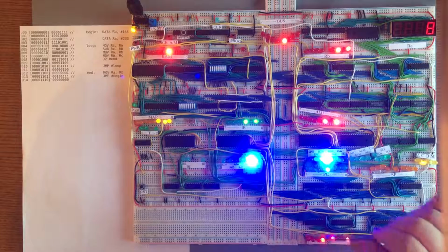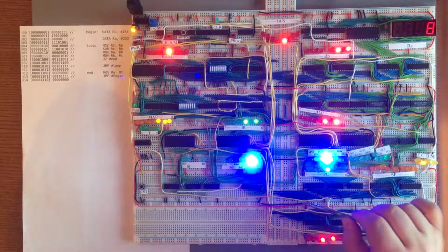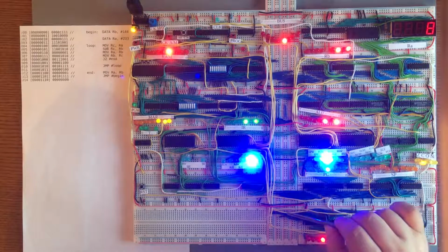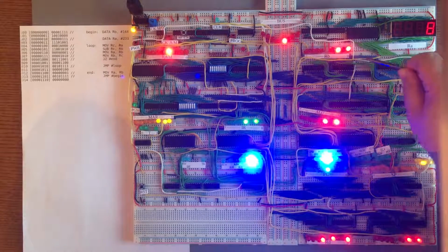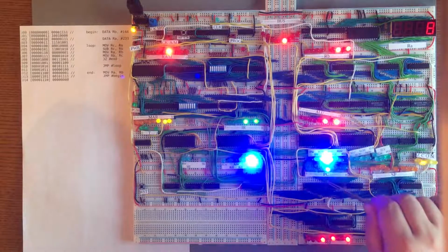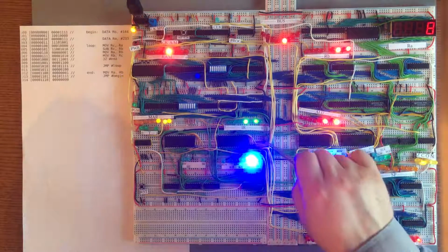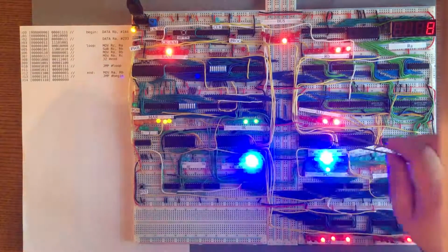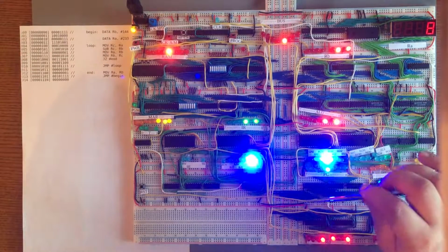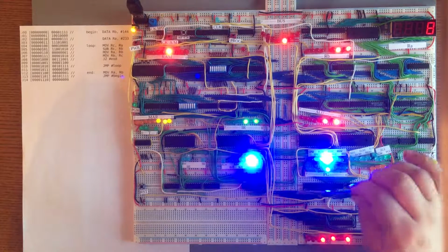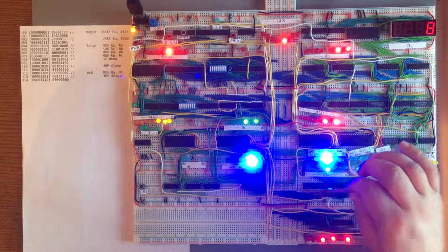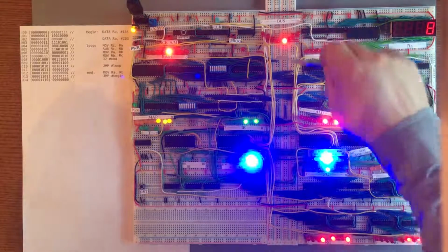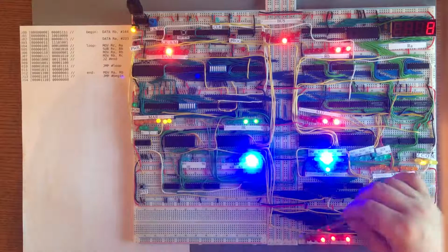I haven't done that because on my CPU there isn't any situation where a component would only be enabling a certain number of bits. Every single component on this computer, all of the registers, the ALU, the program counter, this instruction register doesn't output, but RAM can output. They all assert all 8 bits at once. So I don't need any, let's say, default value on the bus, because I'm always asserting all 8 bits. And so that's the first difference. If you look here on this bus, you won't find any pull-down resistors, because I don't need them.